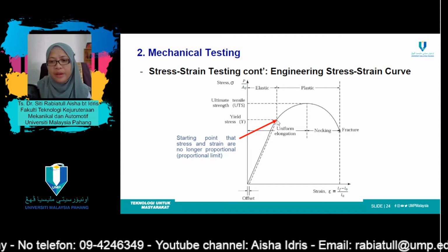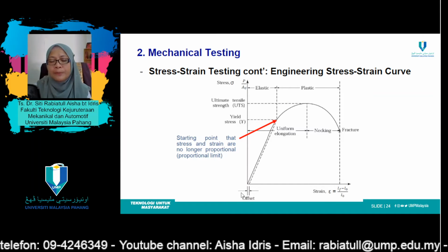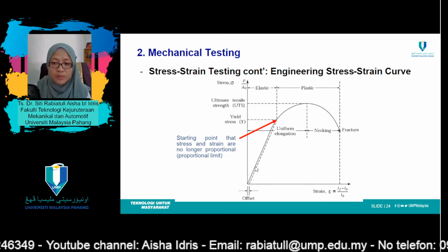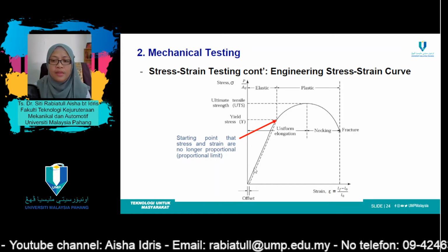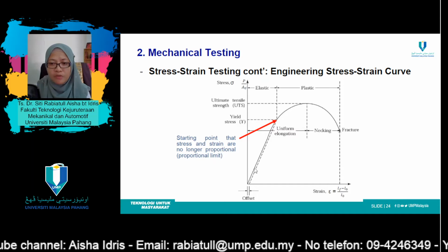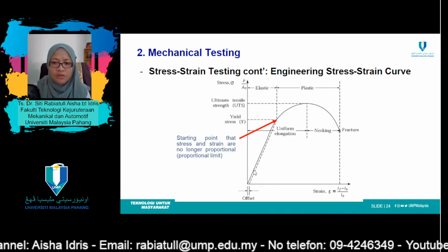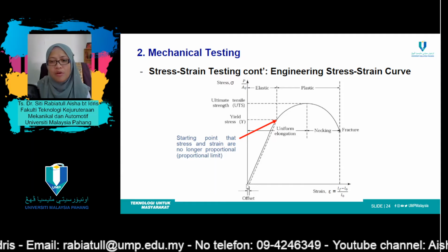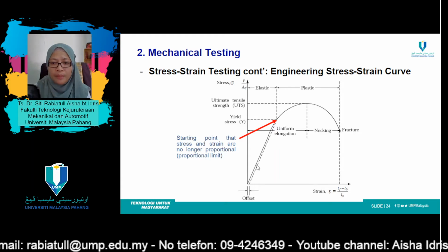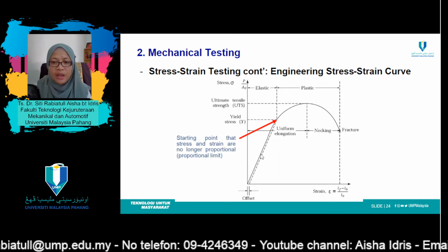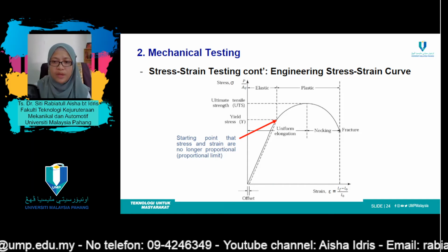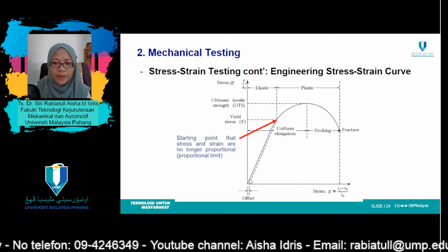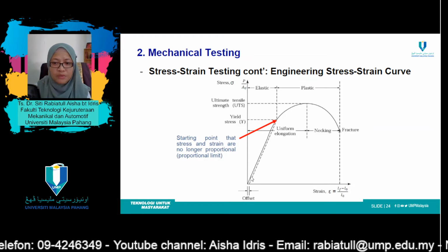stress point there. Let's say a value of force is given to the structure, to the specimen, up to this point, and then you release it. That specimen will go back to its original form following the continuous line over here. After that, you increase the value of force a little bit, then it will go up again until up to this point. Once you release the value of stresses, the value of forces there, it will go back to its original form following this continuous line.